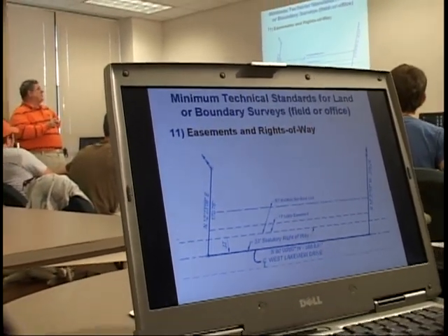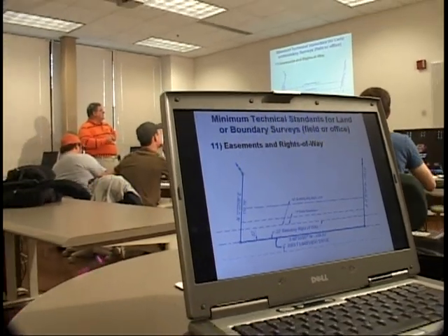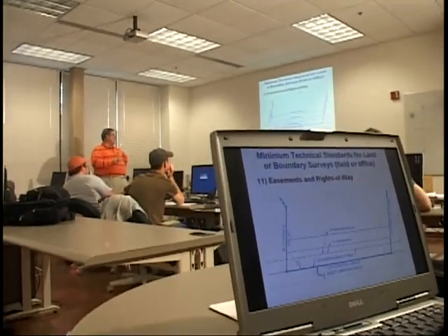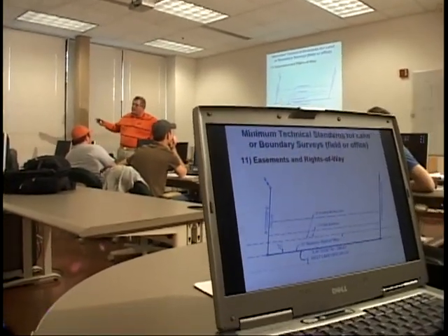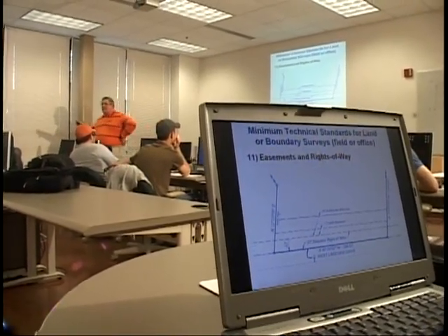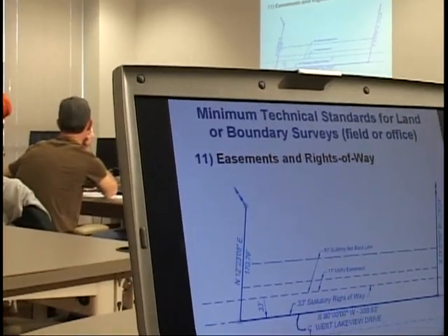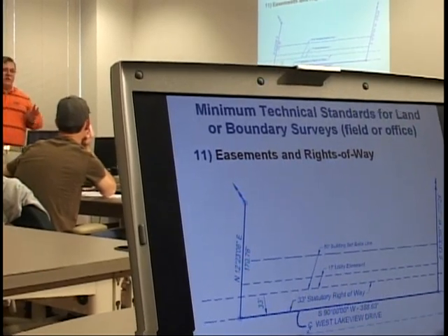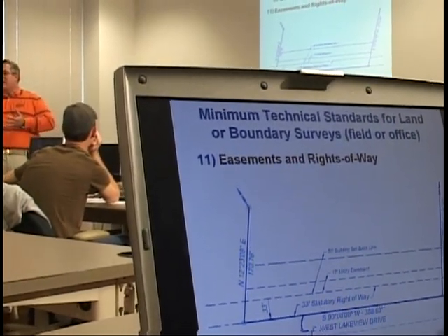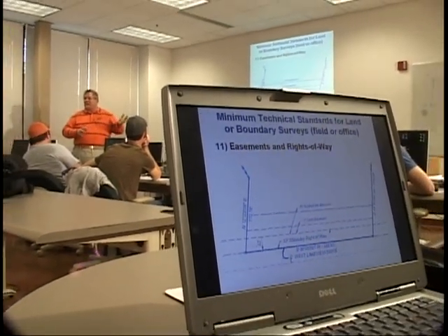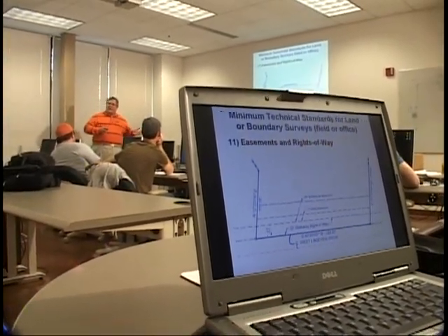As you can see up there, we show the building line, utility easements, and here we're showing a 33-foot statutory right-of-way. Now, what is statutory right-of-way? Well, this is Oklahoma, land of the red man, right? Every section line has a roadway easement that is dedicated by Indian treaty, but they're not all uniform. Different tribes had different rights of way that they granted.